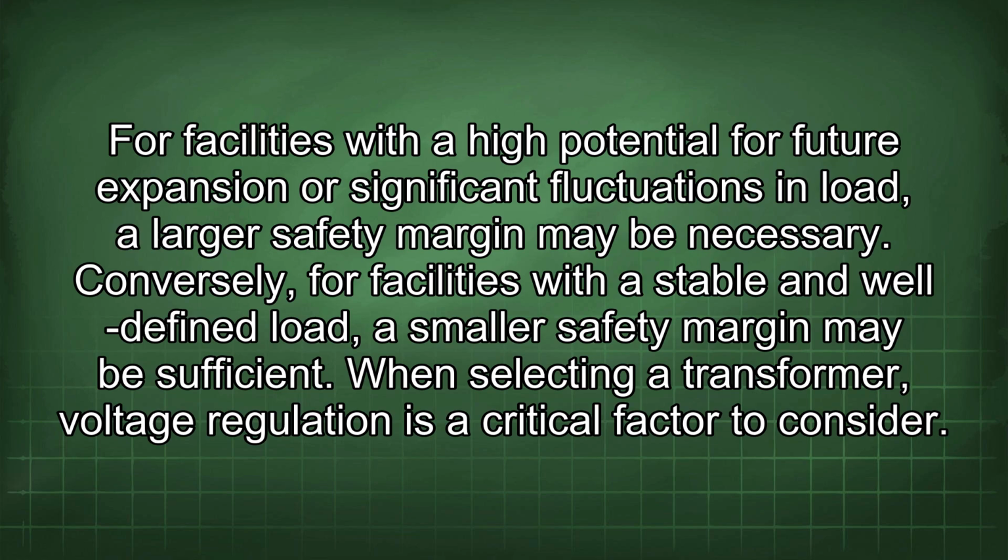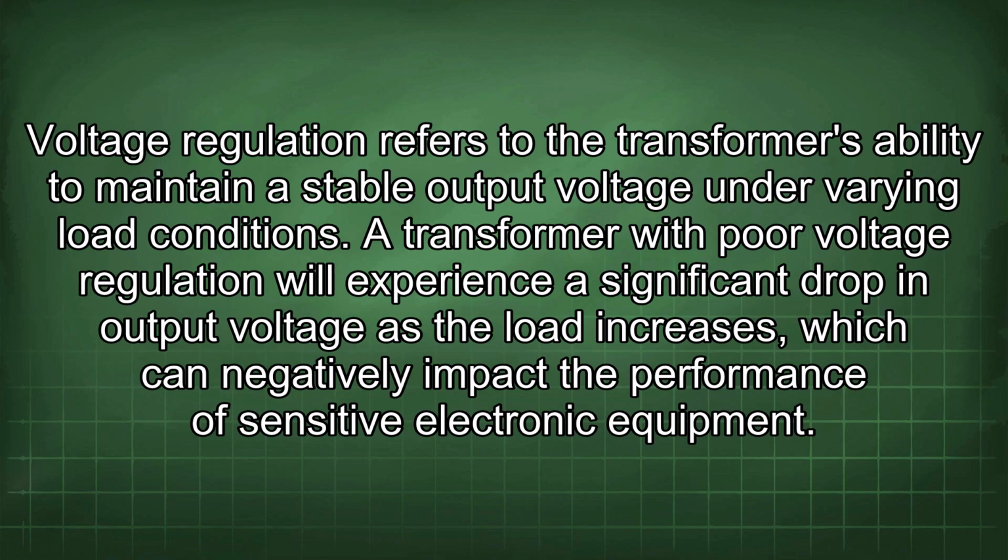When selecting a transformer, voltage regulation is a critical factor to consider. Voltage regulation refers to the transformer's ability to maintain a stable output voltage under varying load conditions. A transformer with poor voltage regulation will experience a significant drop in output voltage as the load increases, which can negatively impact the performance of sensitive electronic equipment.